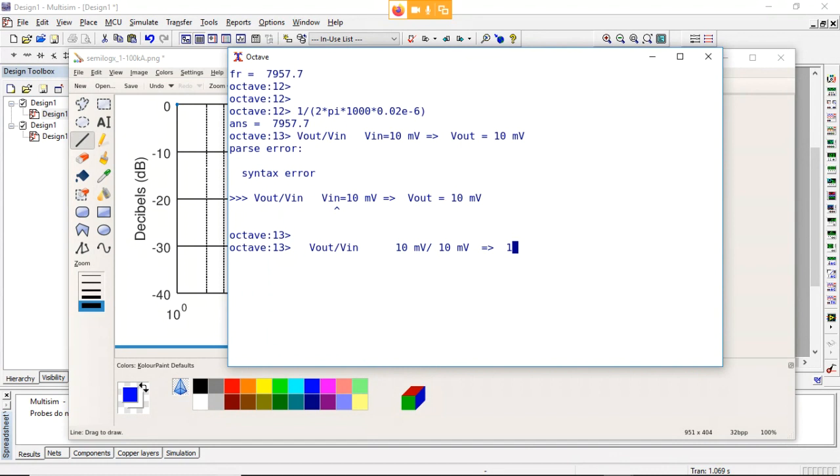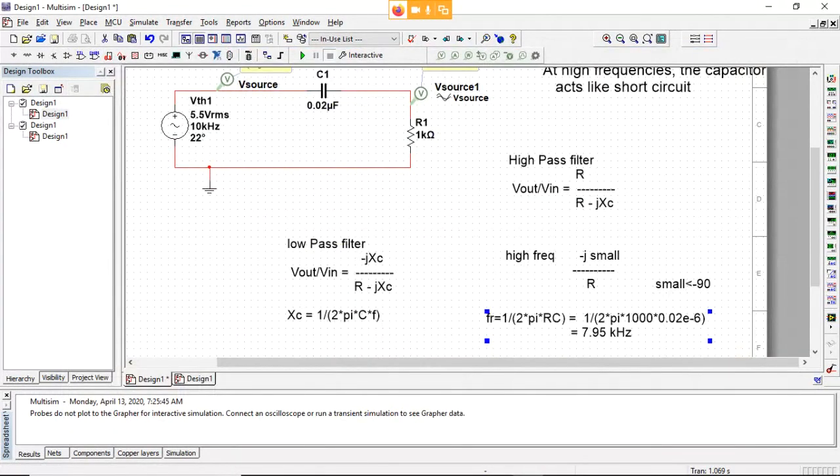And to add in an amplifier, you need something like a transistor or operational amplifier to amplify the input. I've mentioned before, this circuit has capacitors and resistors, and we could add an inductor in there. Those are passive devices, meaning they don't amplify anything. They can only attenuate it. So attenuation means it's going to end up being less than 1.